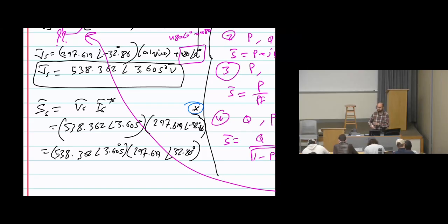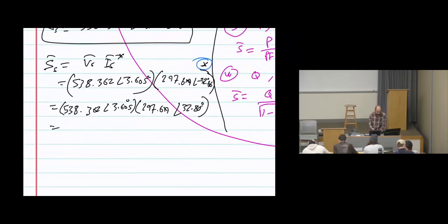If you have difficulties writing the polar form in the calculator, you can multiply the magnitudes and add the angles. So the overall answer will be 16.02 times 10 to the power 3, angle positive 36.465, and the unit is degrees here. The unit is volt ampere. Our target is not to calculate the complex power, so you don't need to convert this to rectangular coordinates. If the question says find the complex power, then when you box your answer, you must convert this to rectangular coordinates.